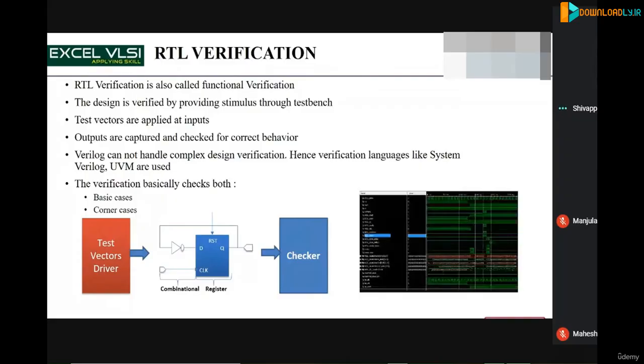Of course, you will use the waveform viewer for debugging the functionality. You will look into the waveforms: with respect to the clock, I gave this data, and then what is it supposed to produce? All this functionality you will check. This is what you do in RTL simulation in order to verify the functionality.